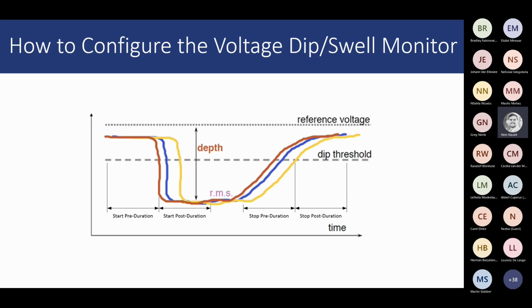Yeah, and again, what's important for you as someone analyzing an event or a dip is the change from a stable condition during the event. Now there can be some changes during a fault, but normally you want to see how the event started and how it restored. You're not that interested in what's happening in the middle per se. You have all the information you need here and at the end. Now, if this period plus that period is longer than the actual duration, so there's no gap in the middle, then you're just capturing all the information. You then have the whole window.